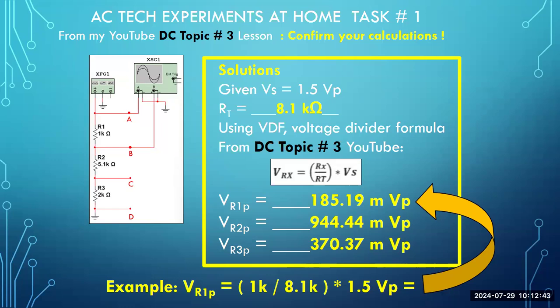Well, it makes sense, I hope, that if we're looking for the voltage across resistor number 1, we use 1K as the numerator and divide by 8.1K, which is our total, in the denominator. We close parentheses. That takes care of your fraction. That takes care of how this voltage is going to be divided across the first resistor. Then you multiply this by 1.5 volts, and hopefully you will get these quantities.